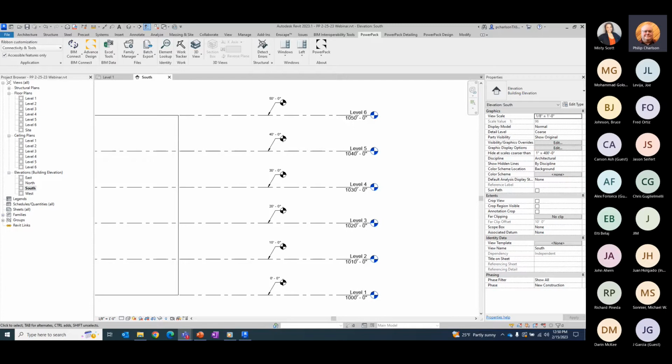Do you have a tool that will check the families for issues like not able to flex it? I don't think so. And again, I'm a big family creator, and I know exactly what you're referring to. The only thing that I suggest to users when I'm training people on creating families is to make sure that you are flexing often when you're developing those families.